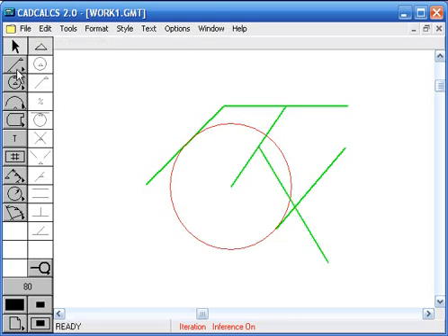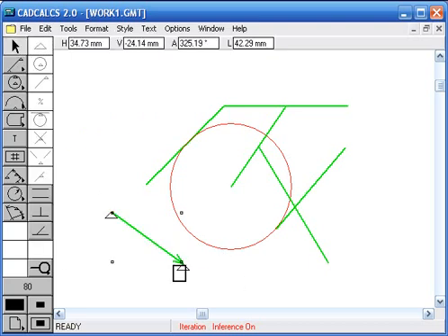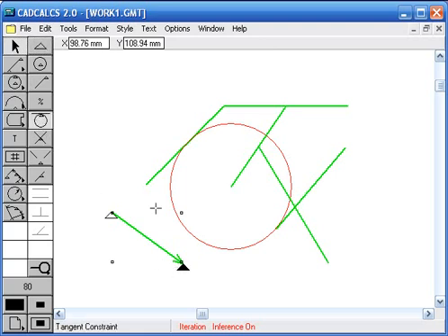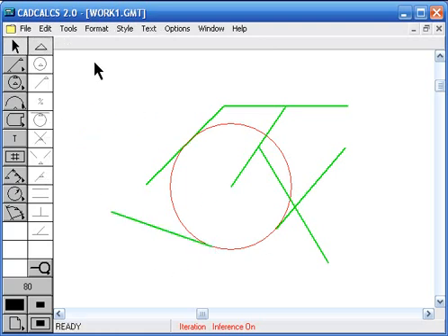Or you created a line and you wanted this to be now tangent to this, so you select the point here and say tangent to this. So once again, there are 3 different ways of constraining. One is to manually constrain using these constraint tools. Second is to infer constraint by snapping to constraints, and third one is late constraint. That means you have created a geometry and you put the constraints later.